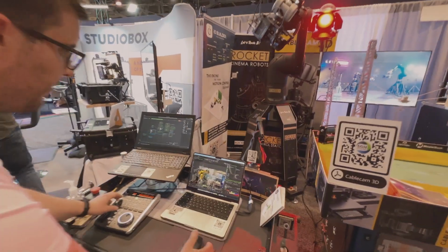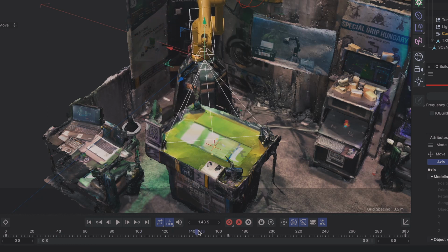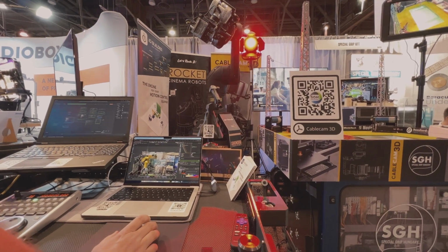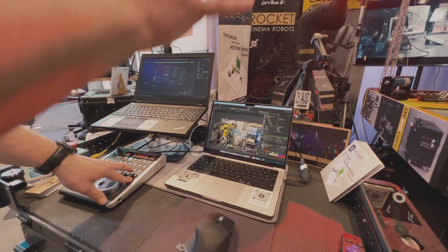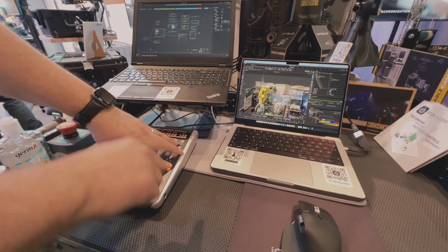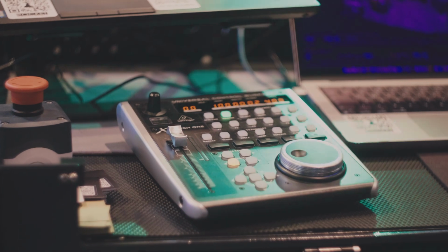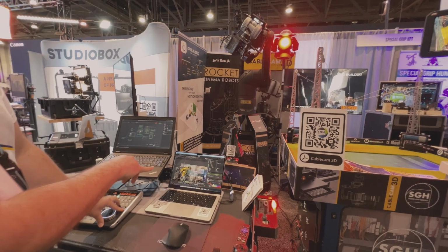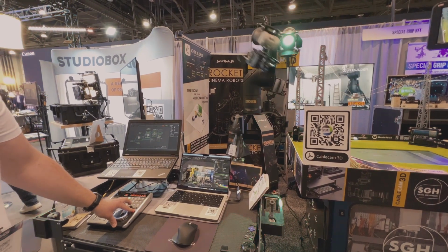Afterwards, we finished with the motion programming in Cinema 4D. We can confirm the framing, so I can grab the playhead here, and I can seek through the animation, just like holding the playhead with the mouse and scrubbing it around. We have 3 seconds of timeline, and I can set the playback rate with a knob on the MIDI controller. I'm turning the knob and it speeds up the movement. So let's say I set the playback rate to 4x or 400%. Because the timeline is 3 seconds long, at 400% the movement will be less than 1 second. And I start to play it back.